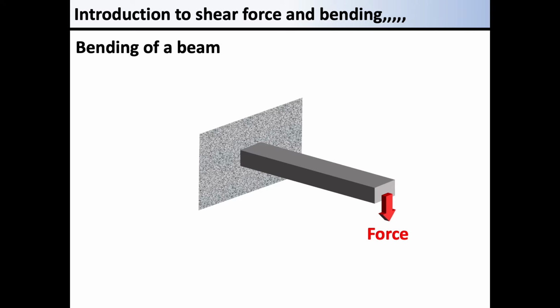In general, a beam is a long and thin rod-like structure. When a load is applied to the structure toward a direction vertical to the longitudinal direction, as in this illustration, the beam bends toward the direction of the load. The method of beam bending determines the amount of the deformation.